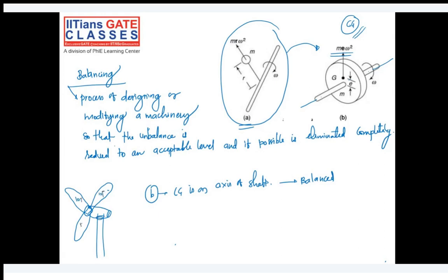If one blade of this wind turbine is quite heavier than the other two, and it is rotating, obviously this rotor will feel an unbalanced force. Whenever it is coming down, it will get a nodding action in the downward direction. For each rotation, you will realize that our rotor is unbalanced, and it is causing a lot of loading in the other parts of the system.